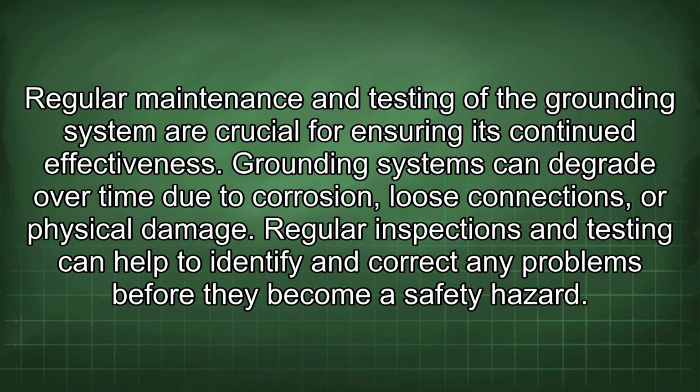Regular maintenance and testing of the grounding system are crucial for ensuring its continued effectiveness. Grounding systems can degrade over time due to corrosion, loose connections, or physical damage. Regular inspections and testing can help to identify and correct any problems before they become a safety hazard.